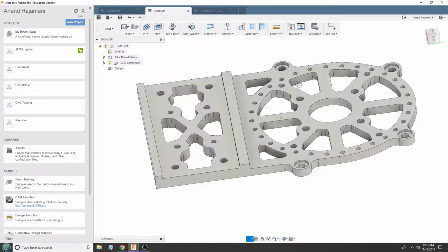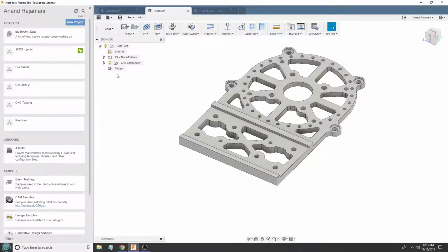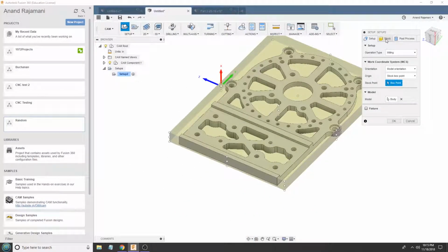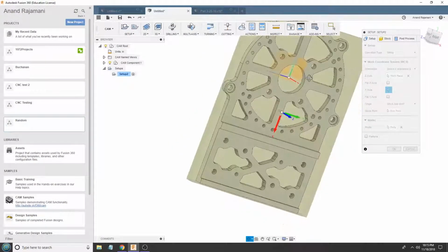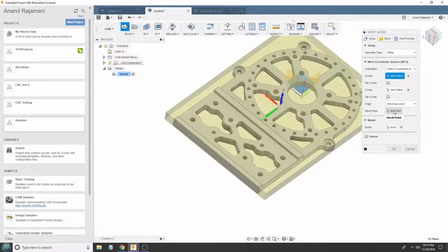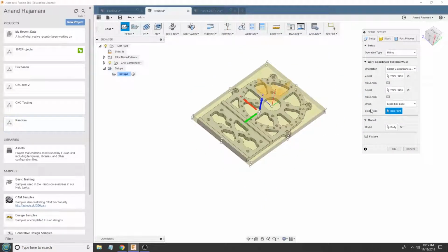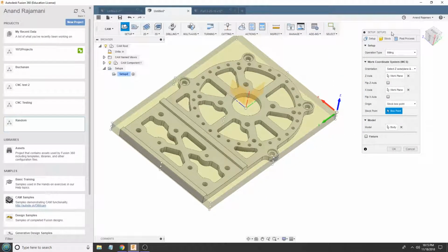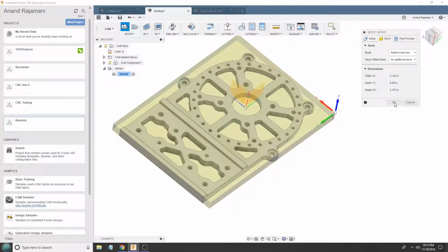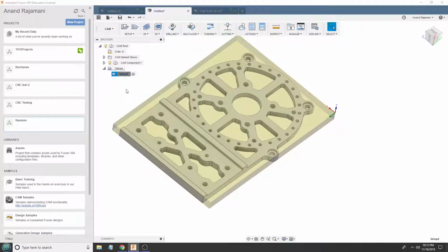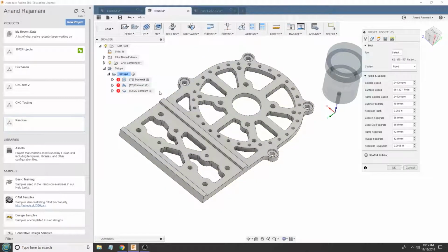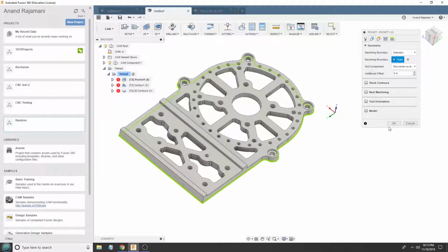Now I want to cam this. Okay, there you go. Let's say I want to cam this guy, right? Same thing. Make a setup. We're going to define our z-axis plane and our x-axis there. And I want to have a stock box point, say over here, because I'm lazy, I don't want to flip anything. No additional stock. Hit OK. Create from template, 3D test, and from here, very easy. I just need to select one contour, which in this case has to be the bottom.